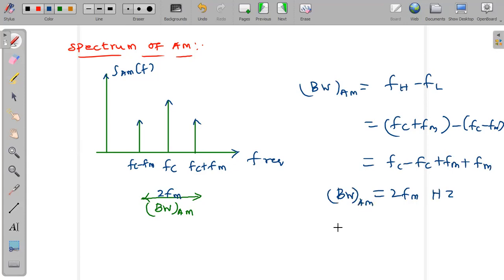So இப்போ upper sideband மட்டும் பார்த்தோம்னா bandwidth of upper sideband it is fm, right? So இங்க இதோட difference fm. Bandwidth of lower sideband component மட்டும் பார்த்தோம்னா so it is fm. And இதனோட amplitude, right? So the amplitude of this carrier component is Ac by 2. So here Ac mu by 4. So here upper sideband component the Ac mu by 4.